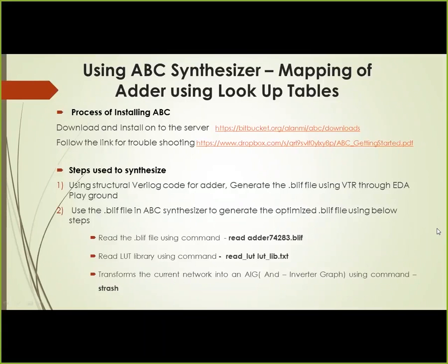Once we were done with the ABC tool, we used structural Verilog code to generate the BLIF file using VTR through EDA Playground. We use structural Verilog code here because behavioral code may not be the best choice if you are aiming to optimize the delay.